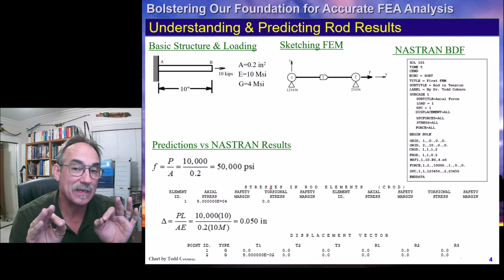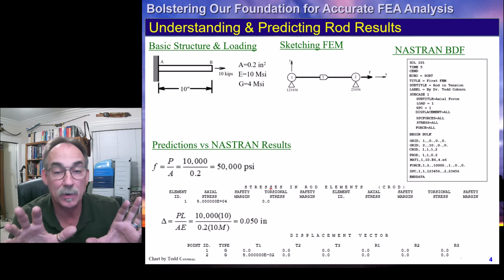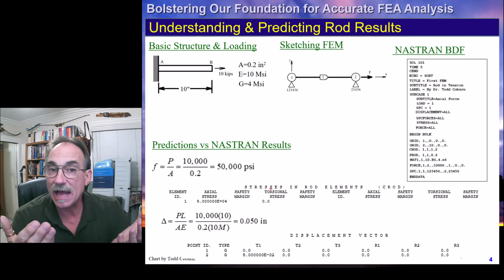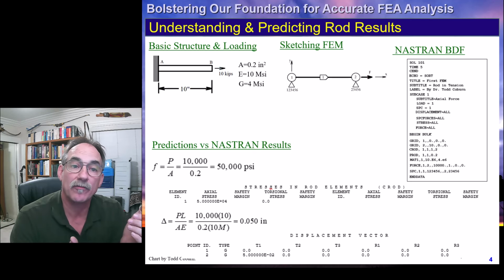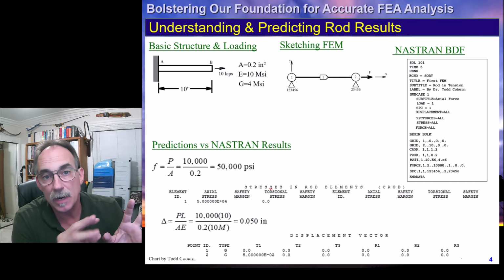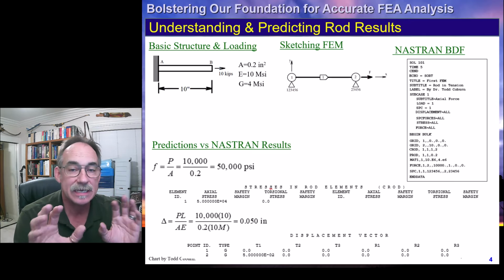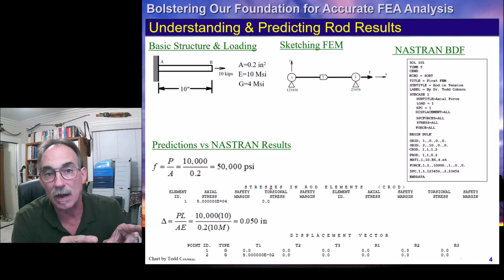And then the next step, if you're using a Patran pre and post processor, is to go and read in that model or drop down a model from Patran, take a look at how that works, practice tweaking that model, bring it back in, and then look at how the results in Patran look versus your F06 file where your written results are.